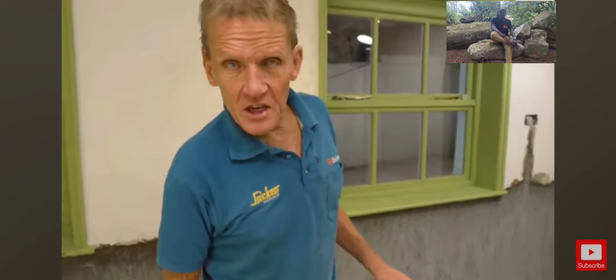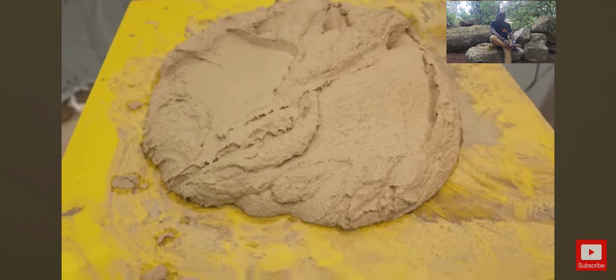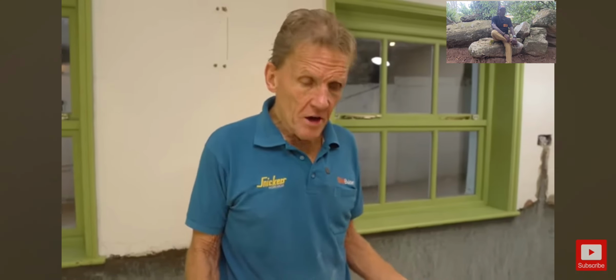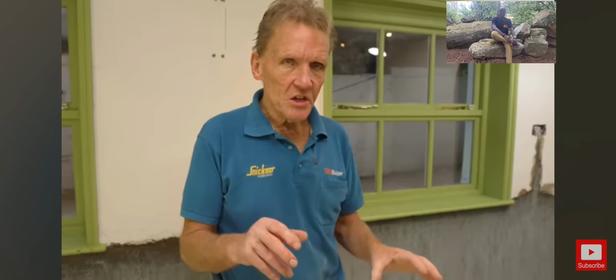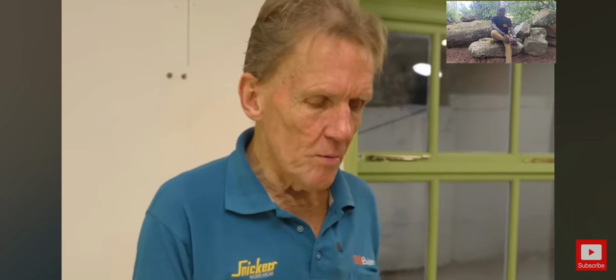So now I've left that TS Plus to dry overnight, it's time to put the high lime plaster on. And the great thing about this lime plaster is that it's kind of breathable, it absorbs a little bit of condensation, moisture from the air, it's warm to the touch. So it's the ideal product for basements which, especially suffering from condensation, because it just absorbs a little bit of moisture and then releases it, almost like a buffer.